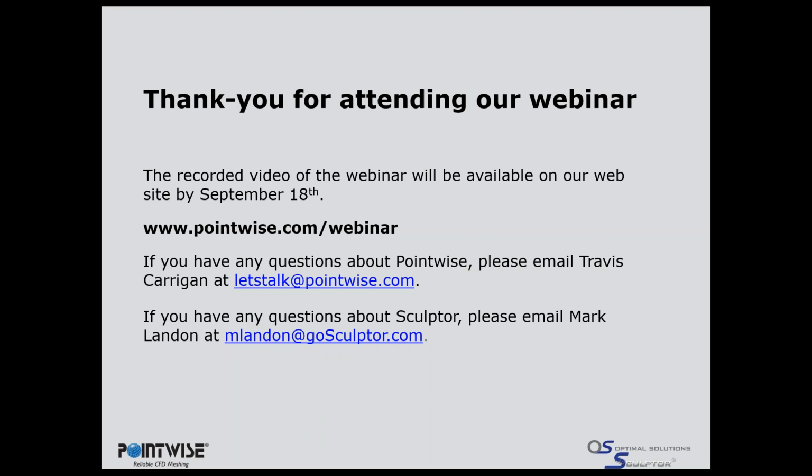What is the quality of the cells where the tires touch the floor? That's a great question. Actually, the quality is not that bad there. There's a couple different ways to handle that, and we've seen a couple of different ways. One is you can clip the bottom of the tire, which is what we did in this case. We just clipped the very bottom of the tire. You can also put a pillar, a very small cylinder underneath the tire that attaches to the ground plane. We didn't do that in this particular case. That case obviously results in the best quality, and what you would do is refine in that region, so you would get some very high quality elements in there. The way that we did it by clipping, you do get a very small angle.